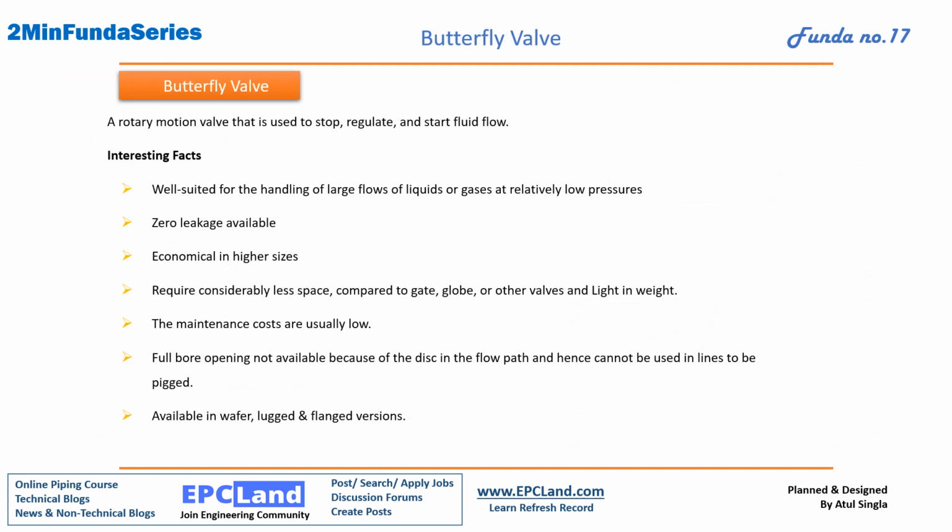Next one is butterfly valve. This is also an isolation valve, a rotary motion valve, which is used to stop, regulate and start fluid flow. Start, stop and regulation. So this is not only an isolation valve, this is a regulation valve also. Well suited for handling large flow of liquids or gases at relatively low pressure. In the next slide we'll discuss what kind of butterfly valves we have, why a few of these we can use for low pressure, and how we can use these kinds of valves for high pressure also.